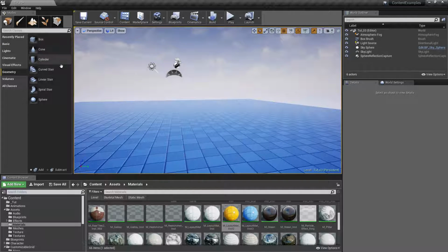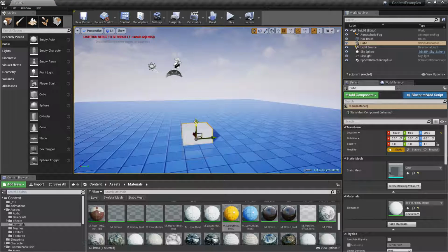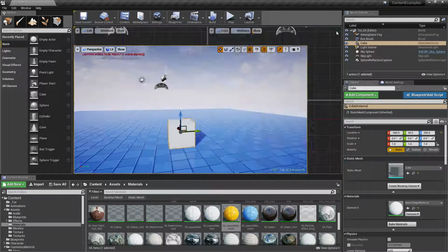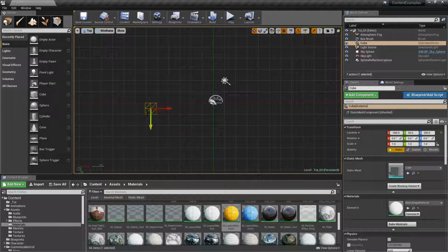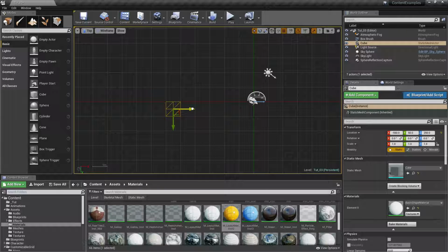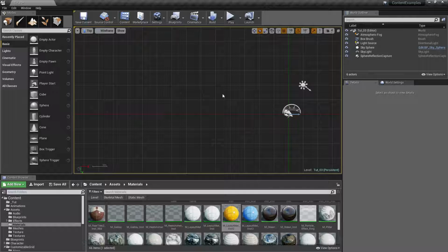First of all, it doesn't matter what we actually use. I could use even a basic shape, but I want to show you how pivot points work. So if we go into, let's say, top view, it doesn't matter that I have regular cube or BSP cube, just for difference. If I alt middle click, I just alt middle clicked here, and I go into rotation, I'm going to rotate about that point, basically. That's what pivot point is. We're adding a new pivot point. And you shouldn't really rotate your BSP brushes like that, because you're going to run into troubles.